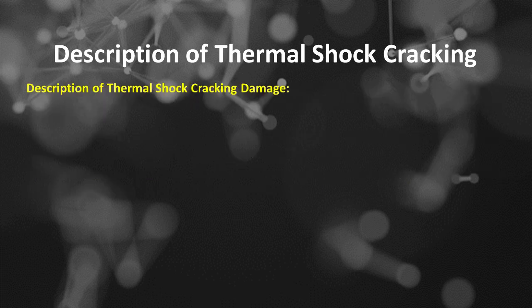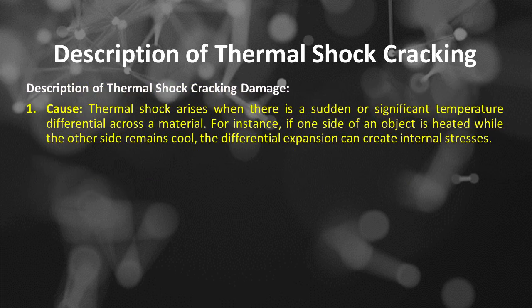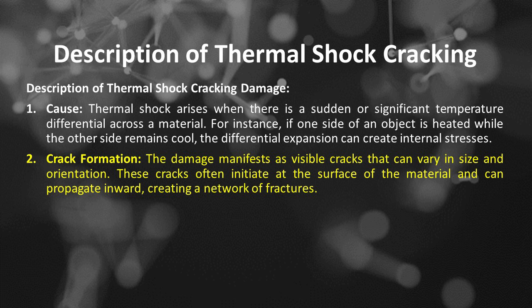Description of thermal shock cracking damage. Number 1 is from cause of thermal shock point of view. Thermal shock arises when there is a sudden or significant temperature differential across a material. For instance, if one side of an object is heated while the other side remains cool, the differential expansion can create internal stresses.